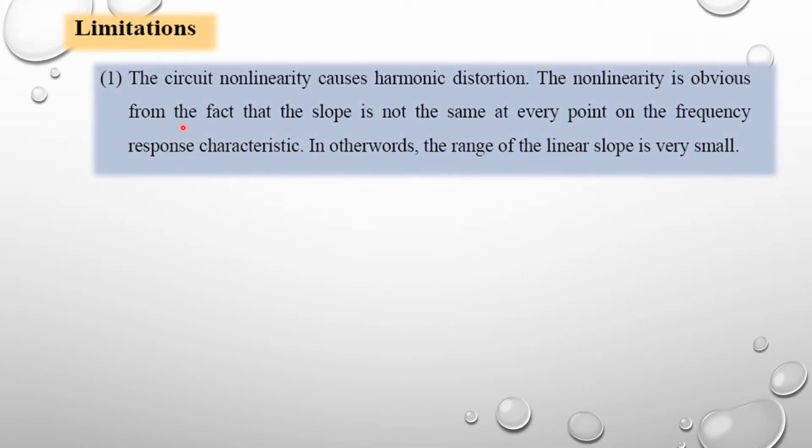In a simple slope detector there are many limitations. The circuit nonlinearity causes harmonic distortion. The nonlinearity is obviously from the fact that the slope is not the same at every point on the frequency response characteristic. In other words, the range of the linear slope is very small.